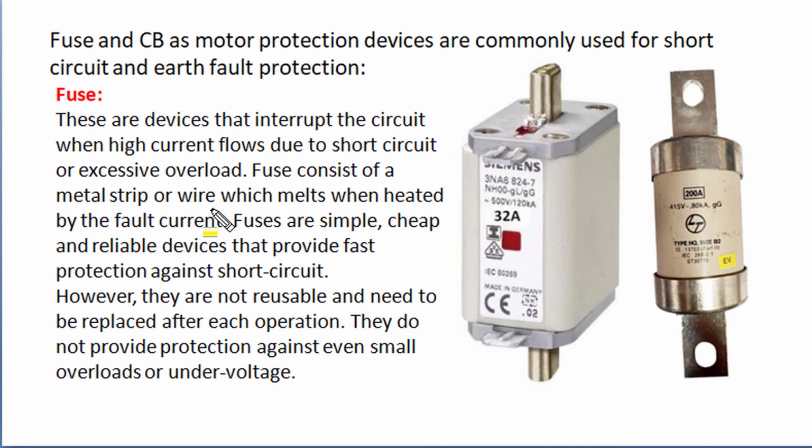The thermal bimetallic strip overload relay protects the motor against overloads, and the fuse and circuit breaker act as motor protective devices against short circuit or earth fault conditions. A fuse interrupts the circuit when the motor operation has a fault of short circuit or earth fault.